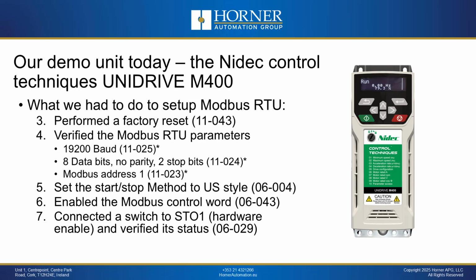Our next step was to perform a factory reset, and we have to perform the factory reset from menu 11, parameter 43. That is our nomenclature, and you can see there on the screen the menu number, the dash and the parameter number. We use that throughout this presentation.